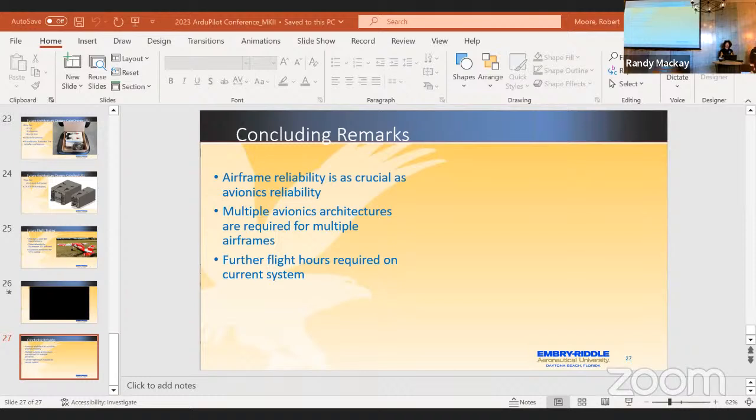So did we encounter any microcontroller failure in this, and were we able to recover from it? So it wasn't a microcontroller failure per se. The DA35 has a lot of vibrations and it does beat the airframes up a little bit. On one of the flights, the primary flight computer, the Cube, came slightly loose because the screws vibrated.